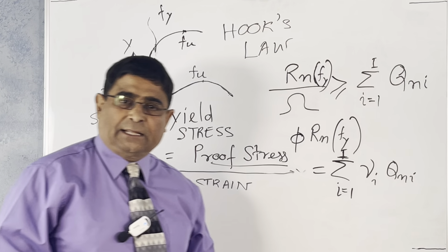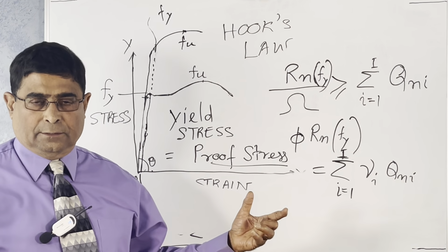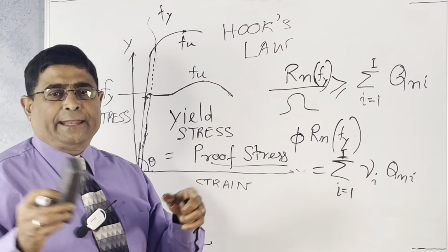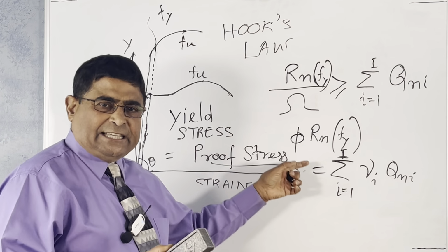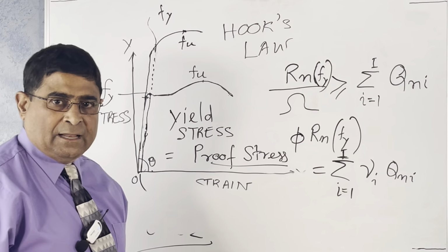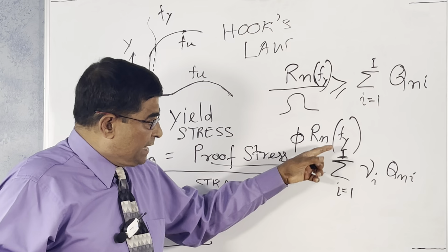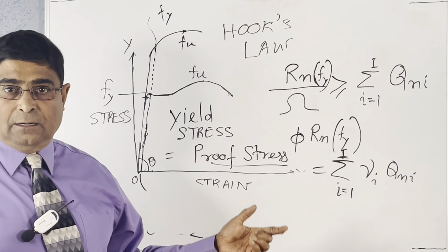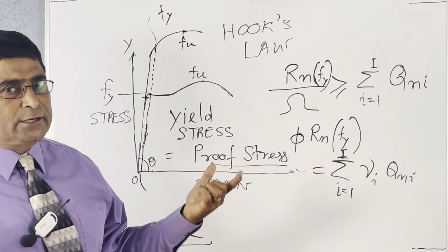Actually, in limit state design, we design the structure for a higher load. Understand? We increase the load and design according to the increased load. Consequently, the stresses developed will be less, right? So that is the meaning. Consequently, the bigger section is ready for higher moment, higher shear, higher torsion.